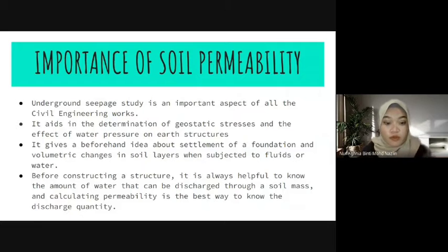Importance of soil permeability. First, underground seepage study is an important aspect of all the civil engineering works. Secondly, it aids in the determination of geostatic stresses and the effect of water pressure on earth structures.